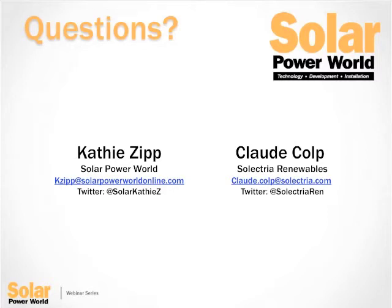Again, another question about the Arcom. Can it be mounted horizontally, such as on its back rather than vertically? Yes, the Arcom box is a NEMA 4 enclosure, so it can be mounted flat on the roof. It's fully sealed. Can the Arcom be offered as an AC combiner as well? No. I think I would actually want to ask that individual a follow-up question, because I don't know where they're going with that. But no, the Arcom box is for the DC side of the system only.